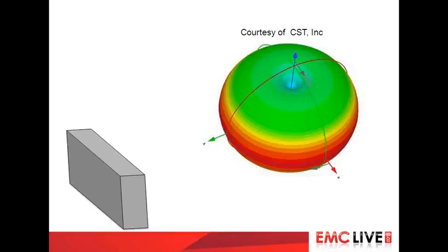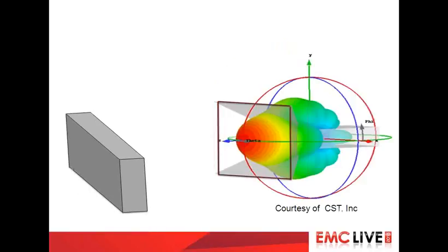However, nowadays, with much more directed antennas, I think you can see here, and again, this is that rudimentary horn antenna, that I haven't angled this very well. If that hits at 90 degrees, if that impinges at normal, much of that power will be reflected straight back at that antenna, will be captured by the antenna aperture there, and end up in the amplifier, which will see a lot of the power it puts forward.